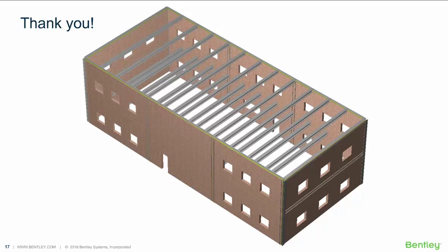Next one I see, how refined of a mesh do you recommend using for the diaphragm and walls? Certainly pertinent because if we are going to in fact mesh the diaphragm as semi-rigid, then it's going to be a shell element analysis.